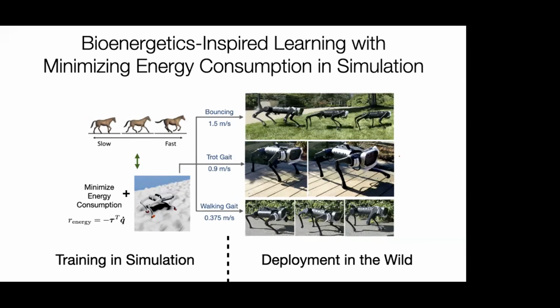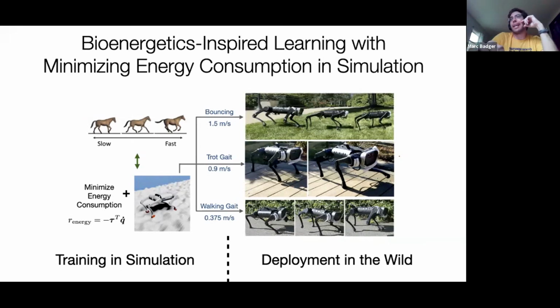Great. Thank you. I think that would be super interesting, to provide the different task rewards like speed or stability, something that could be governed by a vision system based on semantic segmentation of the scenery. So you can say, okay, there's something that I don't recognize coming up, or a patch of grass, go into stability mode.